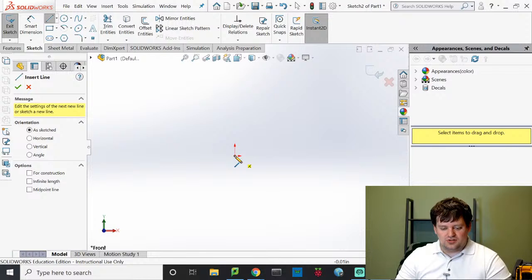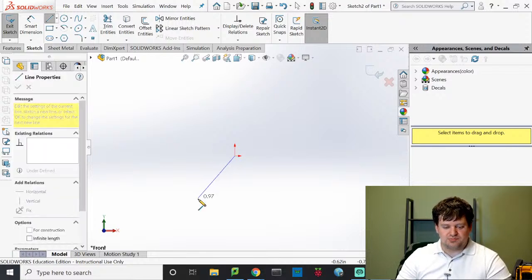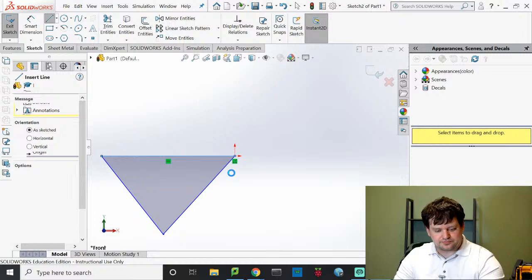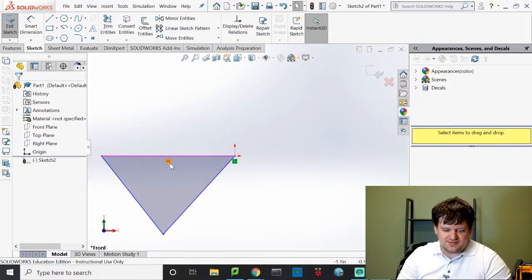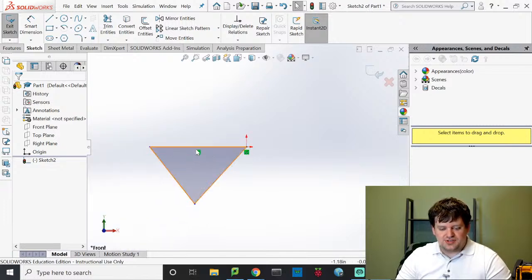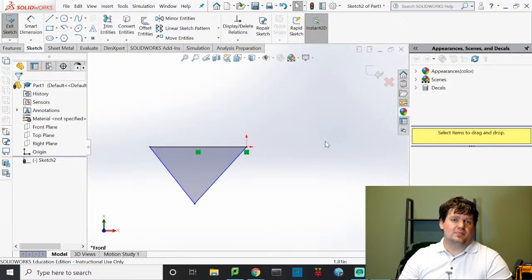So I will start here, which is like up at the handlebars. I'll draw down, and then I'm going to draw up. Okay, and then I'm going to go back because I'm creating just a triangular shape. You notice right here I drew sideways, so this is a horizontal constraint. Both of these points I link directly to the origin. You'll notice this line is now black. That black line means it is partially constrained.